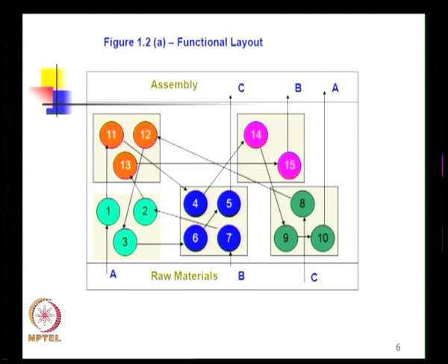Now, in this particular example we have not shown 2 or 3 products or parts visiting machines one after another, but in large systems where we make about 50 to 100 parts or components inside a plant, we could have situations where each machine has a set of parts visiting, and if these parts are not very similar, then the changeover times or setup times are very high.